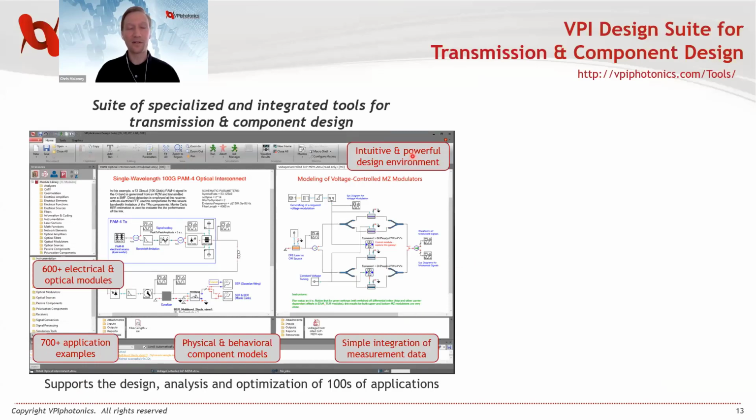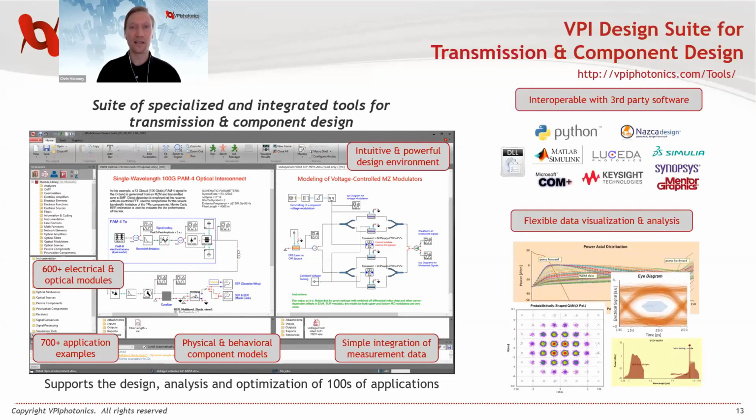But what I want to point out is how our photonic circuits tool is integrated within optical systems. On the right side, you can actually see the design of a photonic integrated circuit, and in particular, this is a Mach-Zehnder modulator. What we can do here is represent this as a building block. So you can see the building block here in our system design. We have our transmitter optics, our optical fiber, and our receiver optics here. So this is all integrated into one design environment.